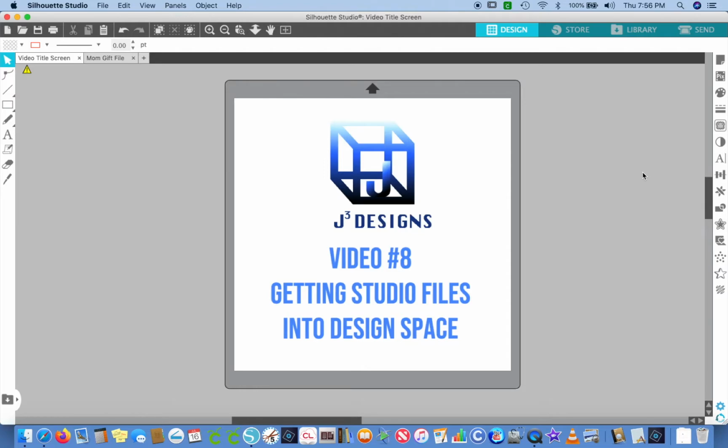upload it. You can get and pay for the Business Edition version of Silhouette Studio, and you can save it as an SVG within Silhouette Studio and then upload it. The problem with that is it doesn't upload at the same size. Design Space reconfigures, so you would have to then go in and resize all of the pieces in Design Space.